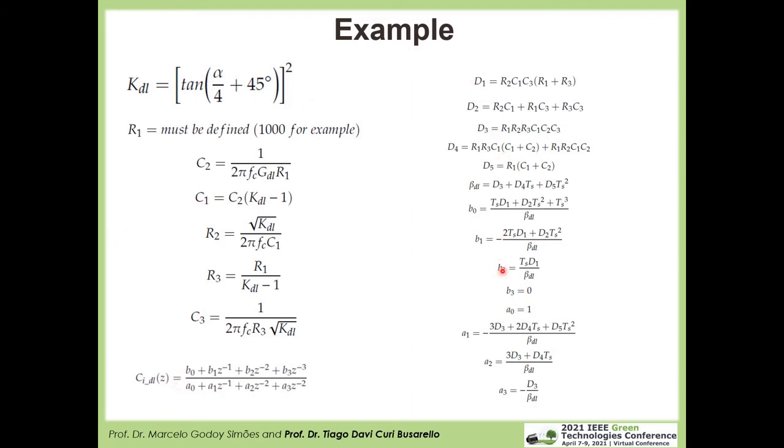All the equations are here, and then we can get our digital controller. Notice that it is a systematic list, it is a procedure. We need to compute one by one and finally get the coefficients B1, B2, B3, A0, A1, all of them for our digital current controller for single lead and the double lead, and also considering the PWM delay.